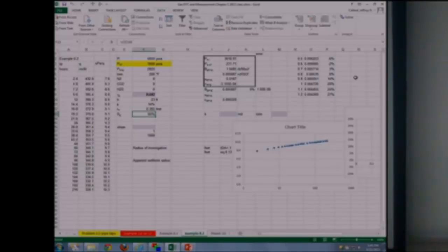Yeah, it's getting close now, we'll figure it out. Okay. Again, this is not typically what you would be doing in industry, where I'm mad the textbook doesn't give me the gas gravity. But it's also smart and studious to learn how to model data. We're modeling the formation volume factor. They told us what it is, and they also told me the reservoir temperature and pressure that it's at, so I'm figuring out what gas gravity. I've also got to assume that all the impurities are 0 here.